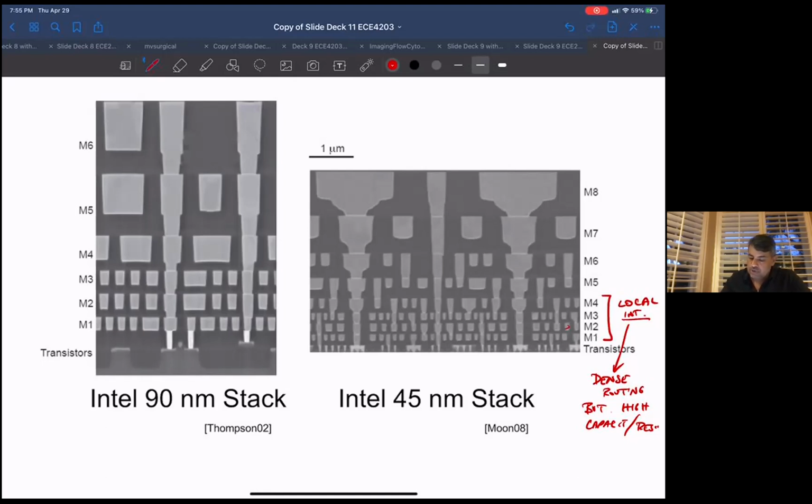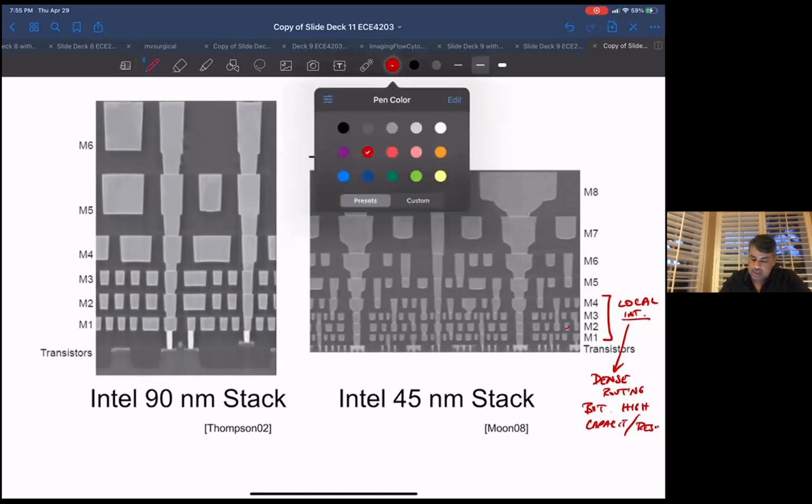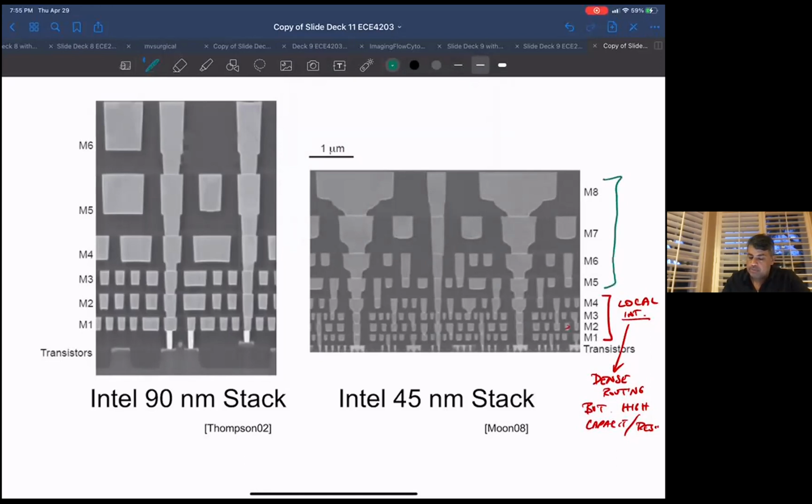So these further top layers, and I'm really generalizing here, I'm not saying always metal 5 through metal 8 is doing this, or always metal 1 to metal 4, but it's pretty typical. These you use for power distribution, ground distribution, and global signals like clock getting distributed. For every line you get at metal 8, you can get, I don't know, like 20 lines in metal 1.